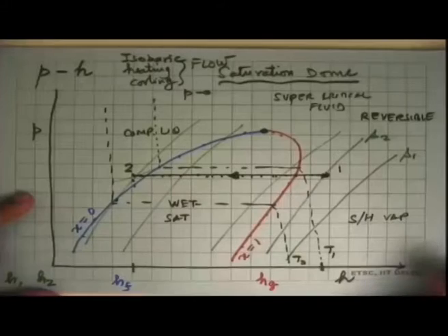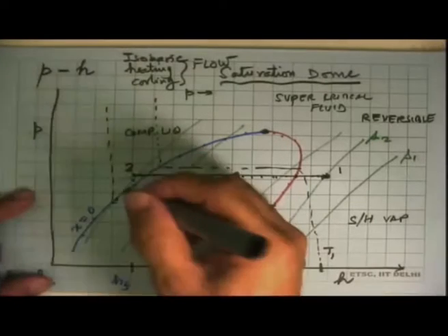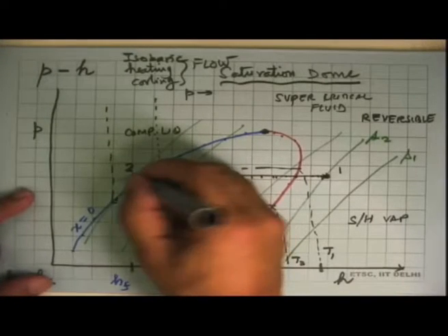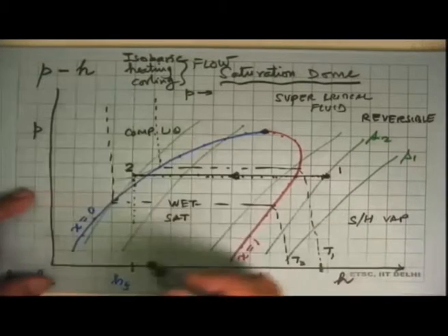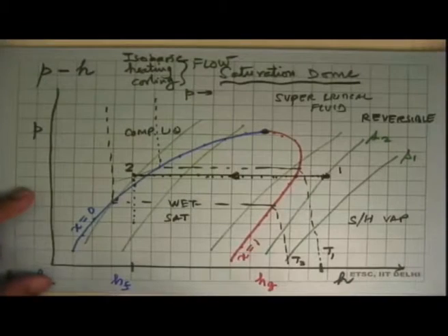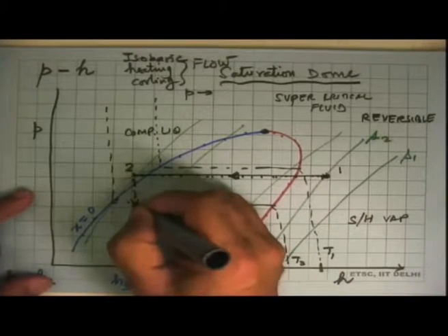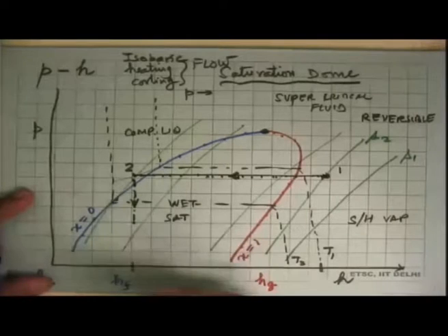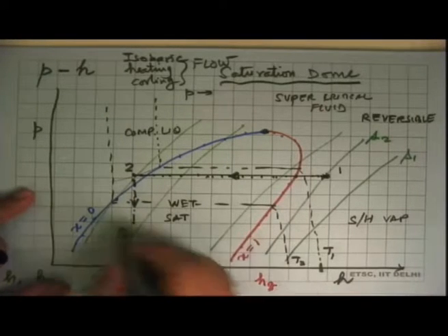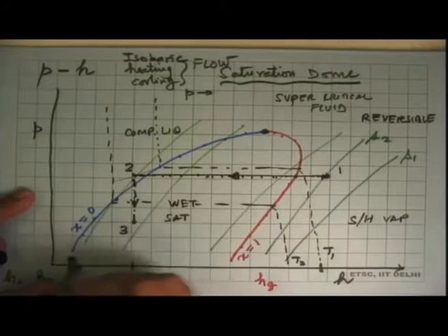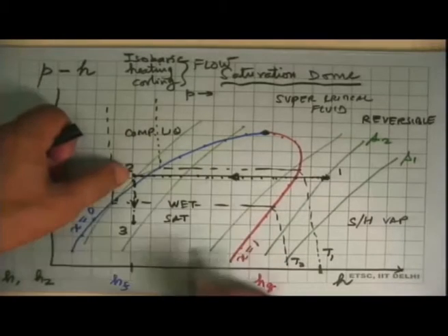So in this diagram, h equal to constant will be a vertical line, and that's what we do in a fridge or an AC, that after this, the fluid is throttled and brought down to a low pressure. And this process will be shown by a broken line because throttling, no matter what, is a hugely irreversible process always.